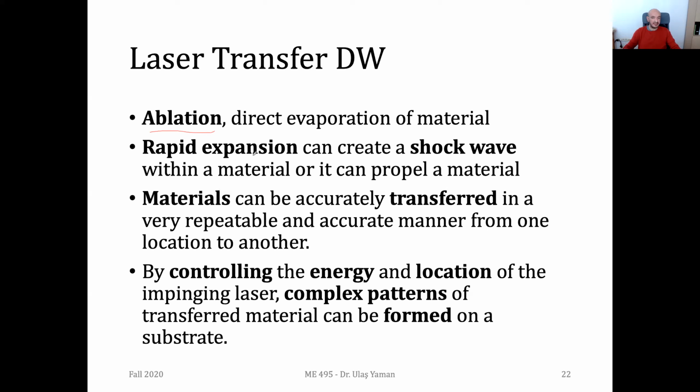With the help of this approach, it's quite repeatable and accuracy is high, and this accuracy depends obviously on the diameter of your laser, the focusing diameter, and also other properties, like the brittleness of your material. You shouldn't be using ductile materials. They should be quite brittle. Otherwise, with a shock wave, you cannot remove that portion from your main sheet of material.